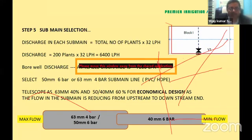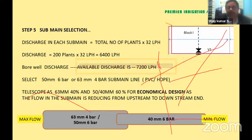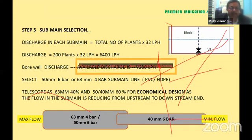So therefore, when we look at the discharge of 7,200 liters per hour, we need to go for either a 50 mm or a 63 millimeter, because the cost difference between a 50 and a 63 mm is not very much. So you can go for a 63 millimeter or a 50 millimeter. More important over here, in order to make the design economical, we can go for what is called a telescopic or an economical design.